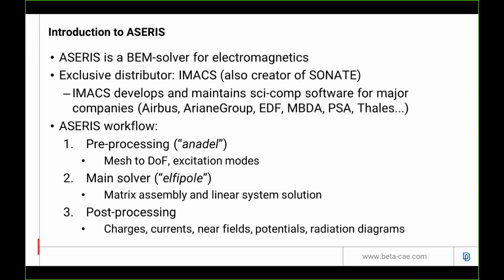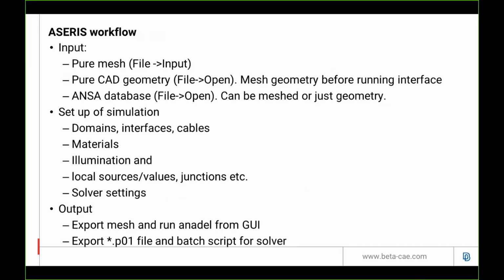The values that we get from the solver cannot be used directly as physical quantities. They have to be derived from these. In the post-processing stage, you can calculate physical quantities like charges, electrical currents, near fields, far fields, radiation diagrams, etc. So the workflow is you have as an input a pure mesh or a pure CAD geometry, but it has to be meshed before running the interface. And you can also have another database which can be meshed or just geometry.